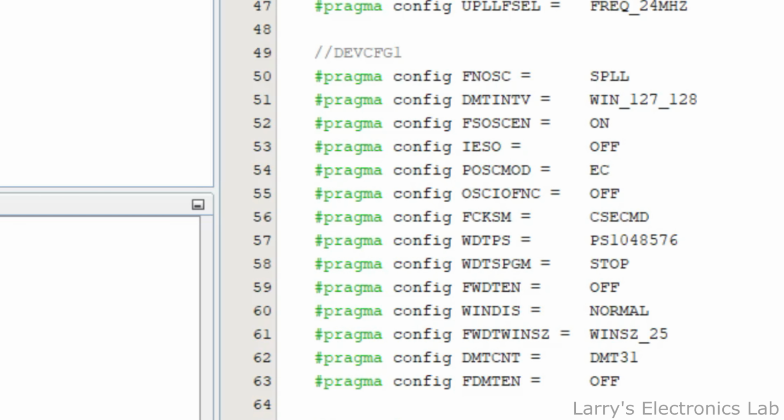But it does a switch over. You can do a 2-stage clock or a dual startup clock, where you can start up on one clock and switch to the other. Usually you would start at a lower frequency and go up to a higher frequency. There are several options available, and we'll cover all the options in the oscillator video.